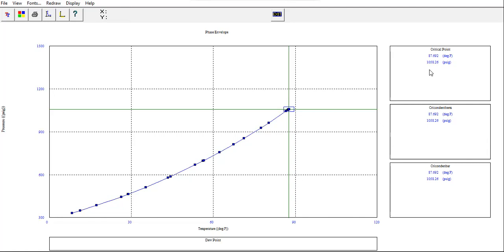So we need to be sure that along the wellbore, from the wellhead through the bottom hole pressure, we can exceed this critical point condition, so we can maintain the liquid form or supercritical form. That's the game plan.